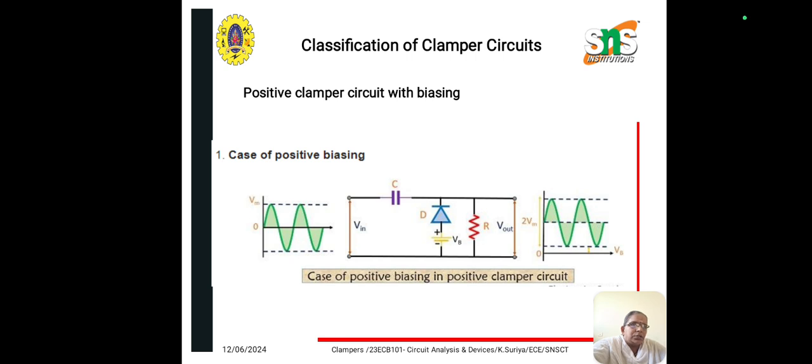As the AC input surpasses the battery voltage, the diode will get reverse biased and hence the conduction through the diode will stop. When negative half of the input signal is applied, the diode is forward biased due to both AC and battery input voltages and it will start conducting. This charges the capacitor with voltage summation of AC input along with the battery voltage. Hence an output voltage level is achieved.